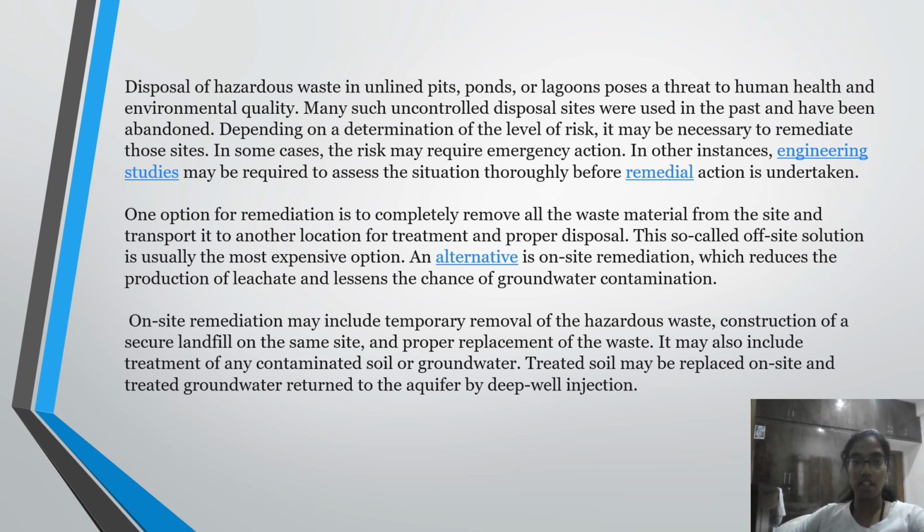In other instances, engineering studies may be required to assess the situation thoroughly before remedial action is taken. One option for remediation is to completely remove all the waste material from the site and transport it to another location for treatment and proper disposal. This is called an off-site solution and is an expensive option. The alternative is on-site remediation, which reduces the production of leachate and lessens the chance of groundwater contamination.